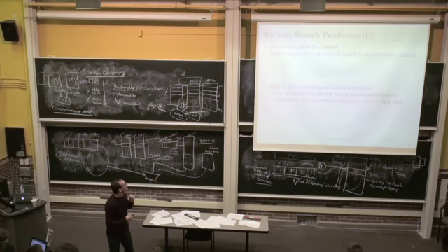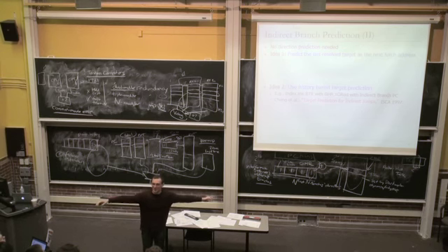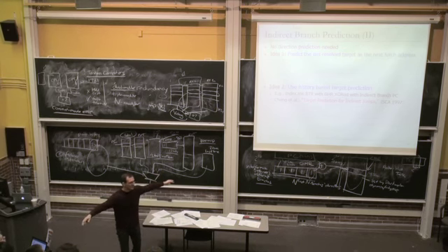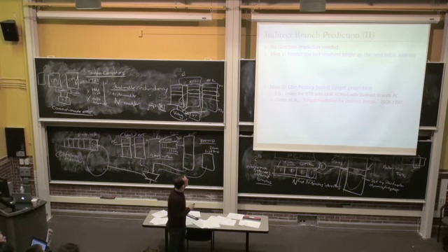I'll just give you 2 of them. You don't need to predict the direction, but now you need to predict what your target is. It could be any 64-bit value, potentially, that's in your code space. Well, any n-bit value where your program counter is n bits. One idea is to predict the last result target as the next fetch address. Last time you executed this indirect branch, the next time you see it, use that target address.